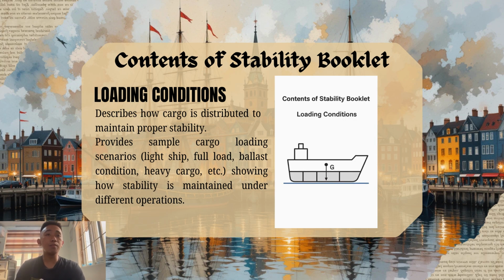Contents of the stability booklet: loading conditions. Describes how cargo is distributed to maintain proper stability. Provides sample cargo loading scenarios like light ship, full load, ballast condition, heavy cargo, and so on, showing how stability is maintained under operations.